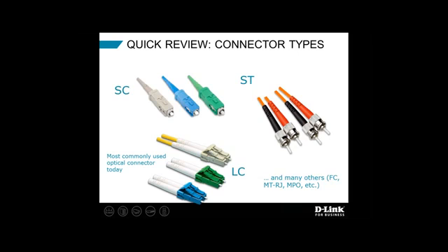We'll look at connectors very quickly here. Fiber optic connectors. 10 years ago, SCs and STs were probably the two most popular connector types. Today, in our industry, I see mostly LCs. I still see some SCs, but LCs have become very popular, largely because of the SFPs, the transceivers that we're going to talk about on an upcoming slide. Most SFPs and SFP plus transceivers today have LC connectors on them. So we see a lot of LC connectors.